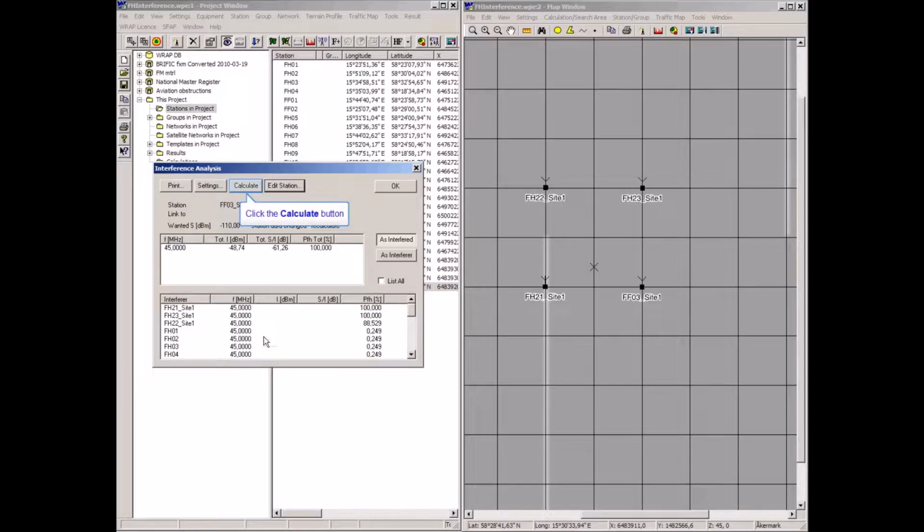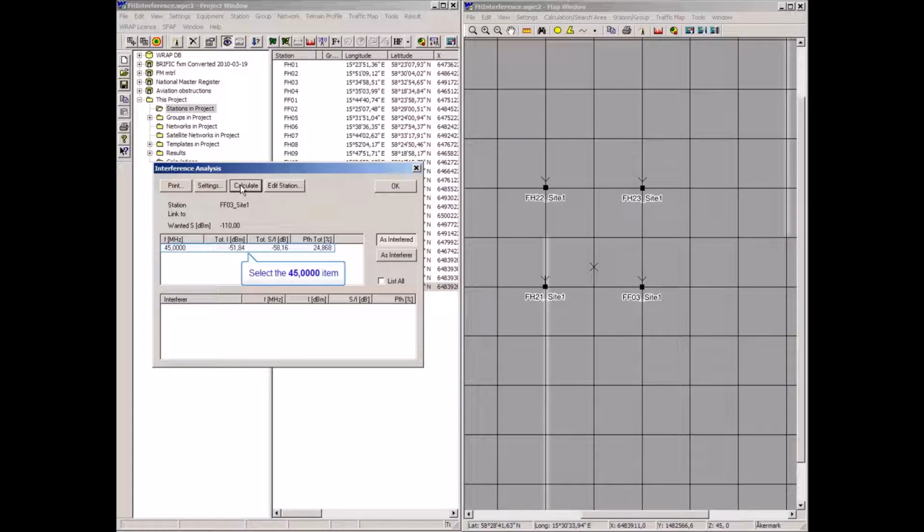So there we are, and now we recalculate and see what improvement we gained from using this configuration instead. Now, the total probability from all the frequency hoppers of interference is about 25% in time.